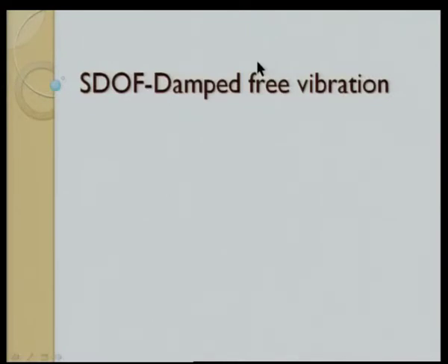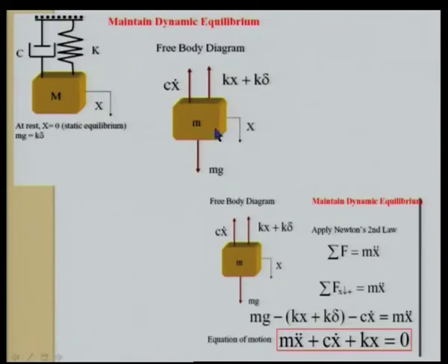Let us come back to a single degree of freedom system where we do not have any damping here. So, this system basically can be represented by mass, spring and a damper. So, we begin the mathematical analysis by isolating this mass and drawing up all the forces and applying Newton's second law. The damping force is always proportional to the velocity of the system in which it is vibrating, that is Cx dot, and mx double dot is basically the acceleration.